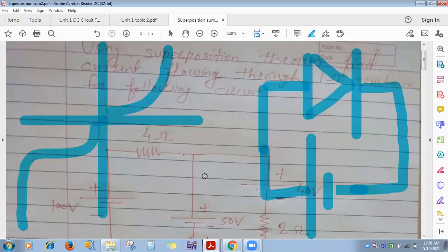What is happening in both the cases? Current direction is different. Whatever the current direction in forward bias, reverse of it is in reverse bias mode. And with the change in current direction, if the characteristics of the circuit change, then that comes under unilateral. So if diodes are in the circuit, and with the change in current direction the characteristics of the circuit change, then that circuit will come under unilateral. In your syllabus, you don't have to analyze unilateral circuits, you have to analyze bilateral circuits.